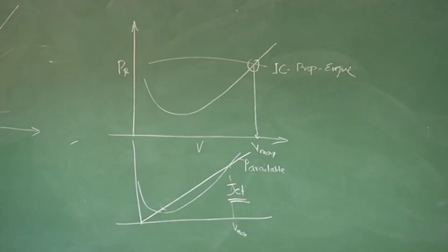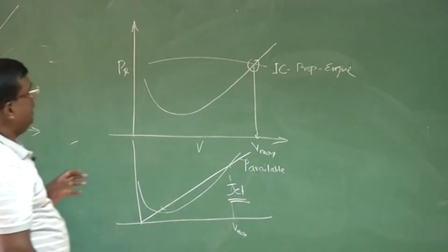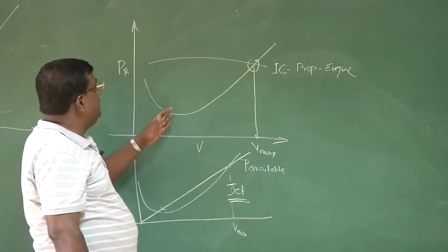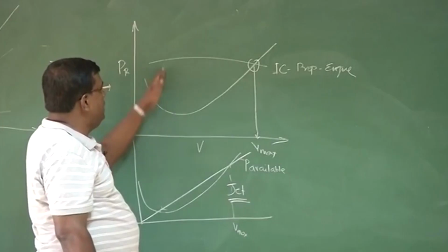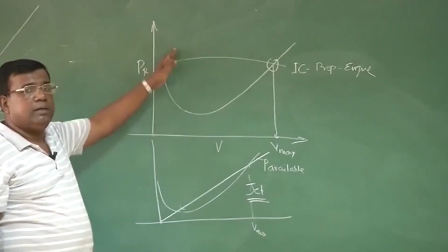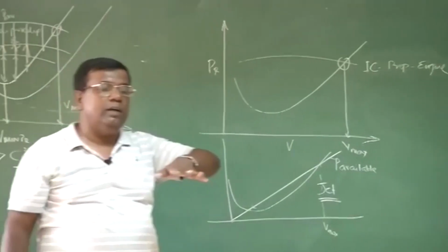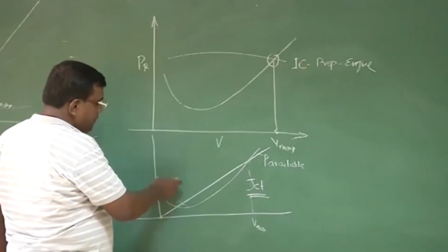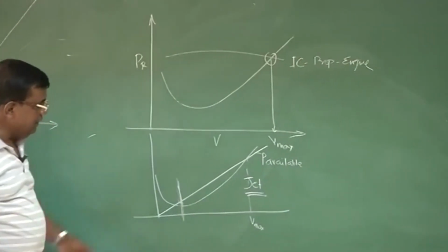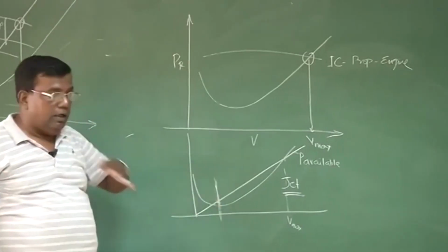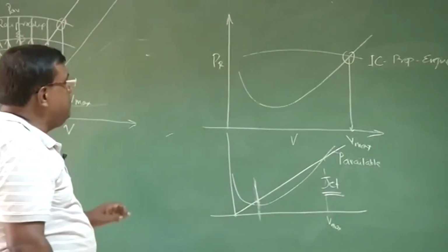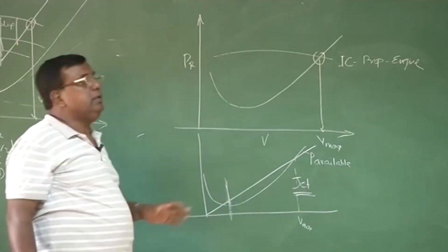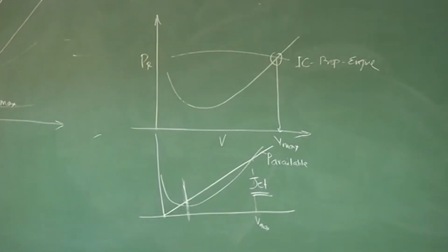Okay. But as a designer, we need to understand also that if I am coming for a landing, right, I'll be operating somewhere here, right? So I have got enough excess power. So in case of any eventuality, I can use that excess power to come out of it. However, when I am using a jet engine, you could see that this excess power near the stall or near where you're landing, that time the excess power relatively is less compared to such an engine. So this is one distinction a designer needs to keep in mind.